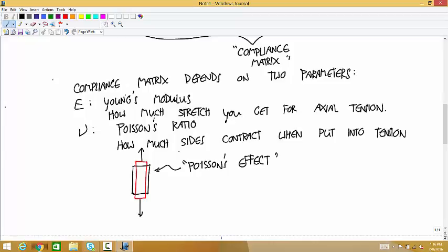But when you think about it, it makes sense that that has become the material that you use in wine bottles, because when you pound something into a glass wine bottle, you're putting an axial compression on it. Most engineering materials, if you try doing that with metal, every time you hit it with a hammer this way, it would bulge out this way, which would break the glass. And so that's why cork is a useful material for that.